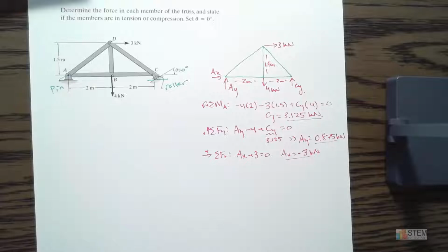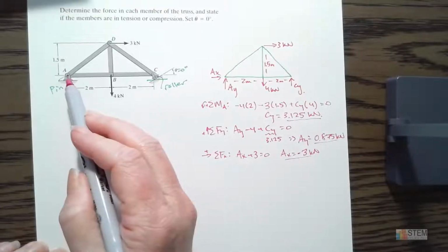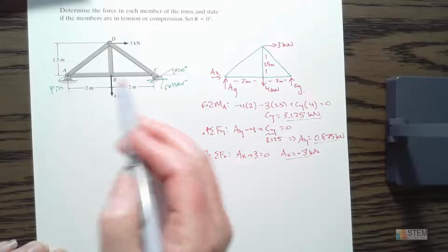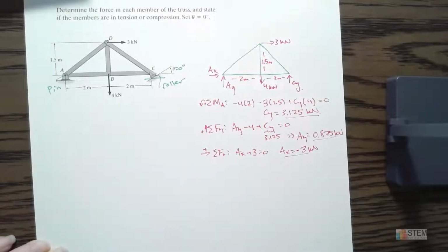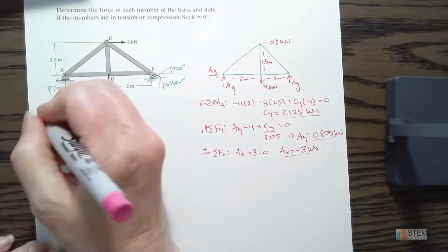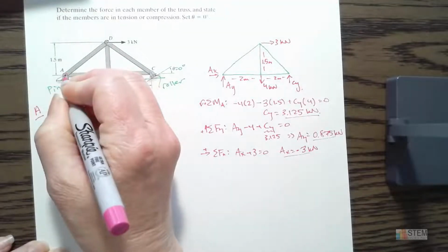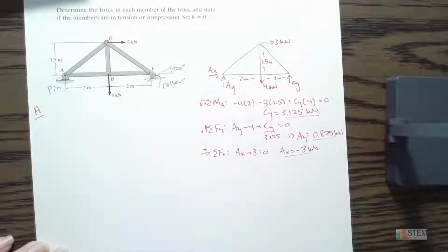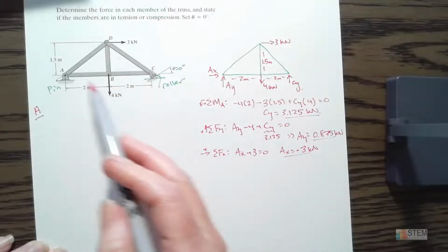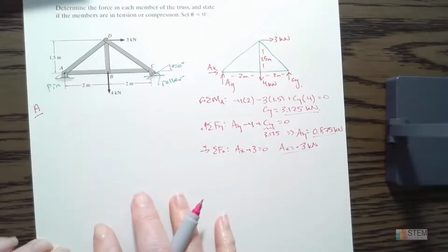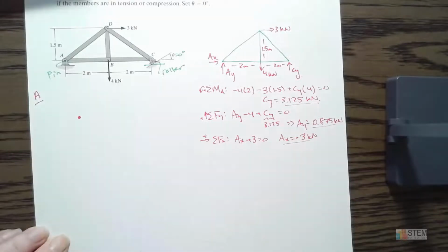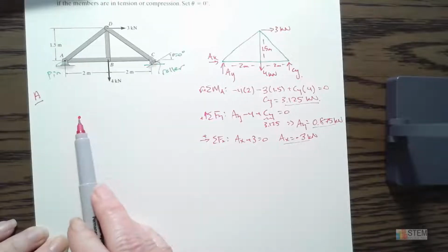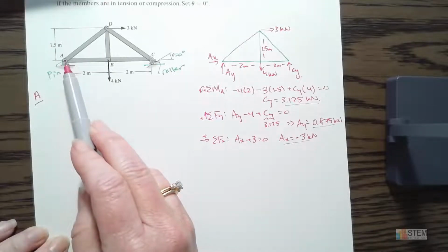The way I always do this is I go through and draw the free body diagrams for all of the joints, and then I look at them all and figure out which one would be best to start with. So that's what I'm going to do here. Let's just start with A right here, and then we'll work our way around this truss. Fortunately, this is a small one, right? We only have 4 joints, so it won't be too long. But these problems can get quite lengthy when they have a lot of different joints. Okay, so joint A right here, let's think about all the forces we have.